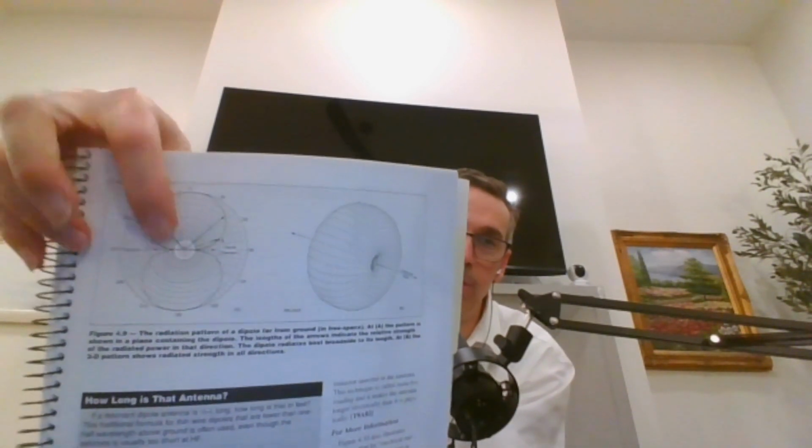And now if you look at it from the center of the wire and then going out the other direction, perpendicular, you'll see how it's going to transmit up and below. So it's above and below. So it'll go each side of the dipole. That just tells you the radiation pattern of how you're going to be able to receive, and depending on which direction you want to aim it at, you might orient it differently.